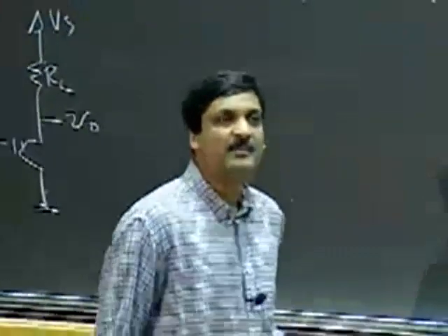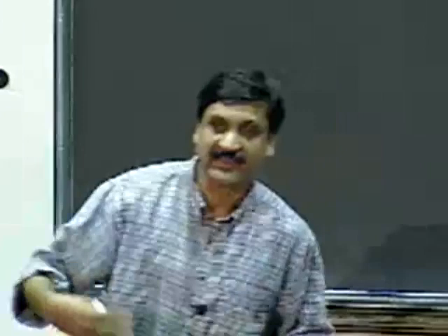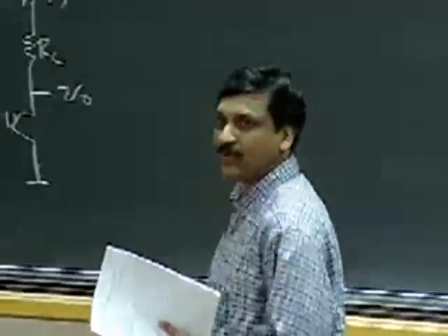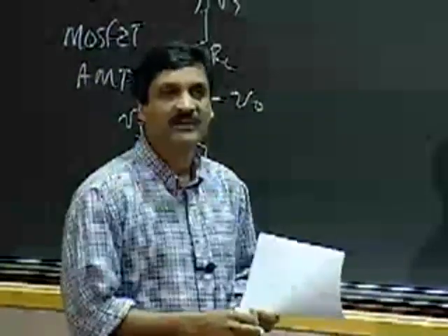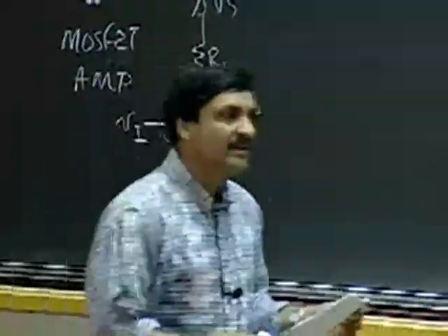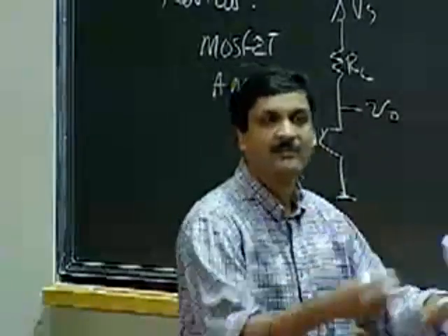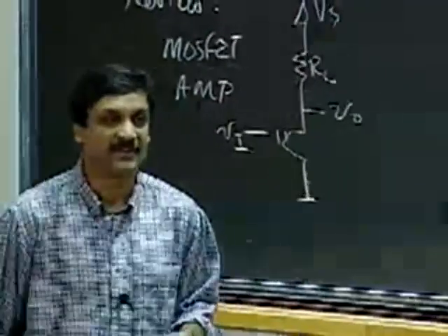There are several other common patterns. The voltage divider is a common pattern. We keep running into that again and again and again. The Thevenin form, a voltage source in series with a resistor, is another very common form. The Norton equivalent form, which is a current source in parallel with a resistor, is also very common. And it behooves all of us to be very familiar with the analyses of these things. Voltage dividers in particular are just so common that you need to be able to look at it and boom, be able to write down the expression for voltage dividers.